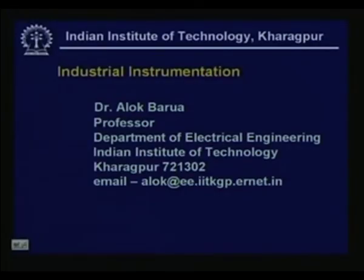Welcome to lesson 24 of industrial instrumentation. In this lesson we will consider piezoelectric sensors. Now as you know, piezoelectric sensors are based on piezoelectric crystals, right? They have a property that if you apply a force across the surface of these piezoelectric crystals, I will get a voltage, and this process is reversible. That means if I apply a voltage, I will get a force also.